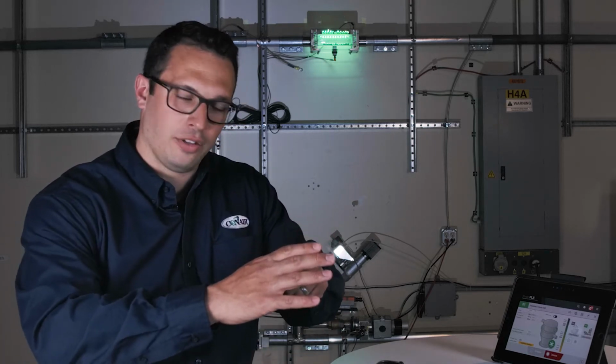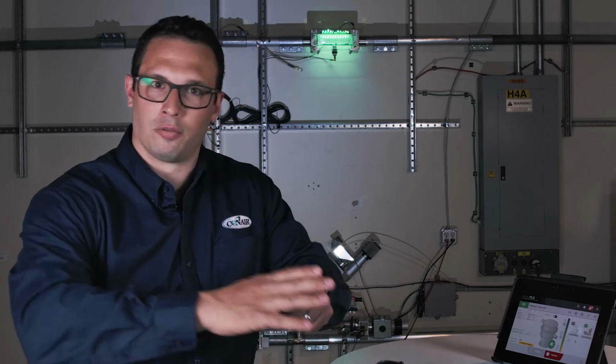Now, if you take your hand, you remove it from the probe, put it back down, remove it, put it back down, what you're doing there is you're breaking a deep vacuum state. You're breaking a vessel within vacuum to atmospheric pressure. When you break vacuum to atmospheric pressure, you have an inrush of air. Physical air has to enter that line, enter your vessel or enter the material handling line in this specific case, to be able to alleviate that pressure differential.